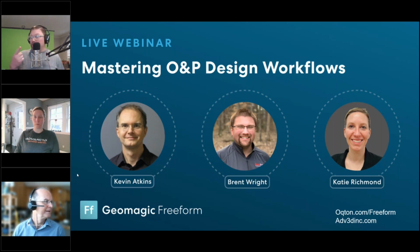And I think that's a good point too. Katie and I have used the auto surfacing on a custom component, but we want to potentially make it parametric. So you may have something that you really like in the organic space, you auto surface it, and then essentially reverse engineer it in the parametric space, because you can export as a STEP file and grab curves and cross sections and all that stuff. So it is a very, very powerful tool